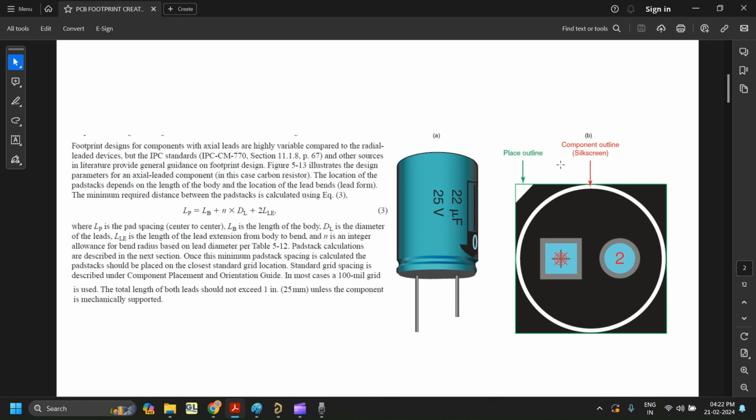Another method is also there, that is a tricky method. What you have to do is select an alternative part for the component which should be pin to pin compatible, and sizes should also match. For that kind of component you can refer to the alternative part datasheet and create the footprint. This is not a recommended method because sometimes you will create errors, because some datasheets will need special footprint recommendation. For those cases, you have to directly approach the supplier and ask what the footprint recommendation is.